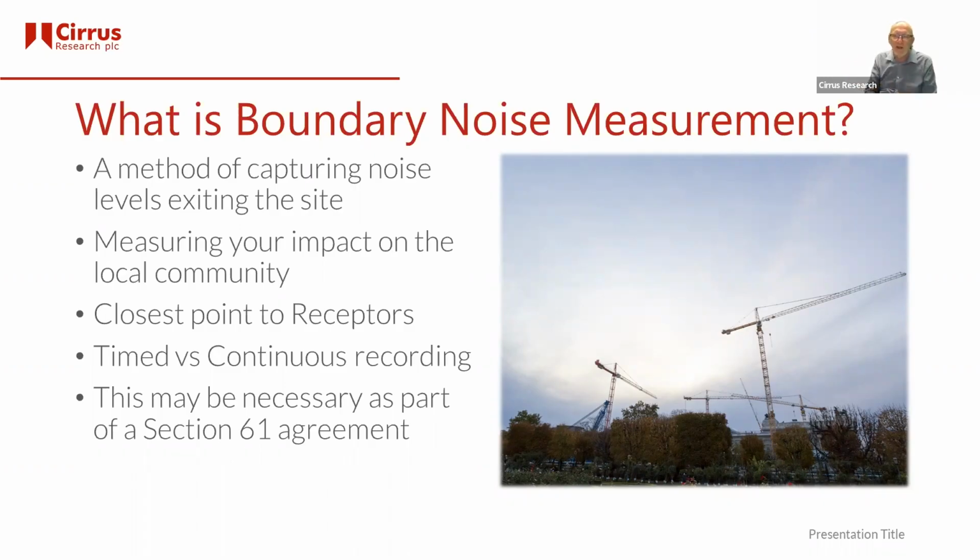If we were on a construction site in the middle of nowhere and the nearest house was 3 miles away, we wouldn't be as bothered as if we were in the centre of London, near some housing, demolishing an old school and building a new one. So we've got lots of housing all around us. What we're interested in is not how loud it is inside the site as such. What we're interested in is what is escaping, what is exiting the site and actually affecting your neighbours. We're doing that by putting the monitors on the boundary, measuring the impact as closely as we can on the local community.